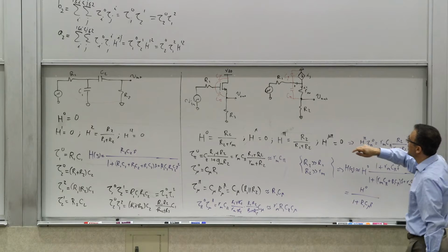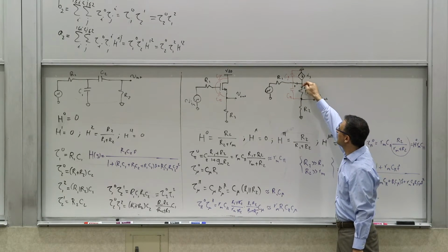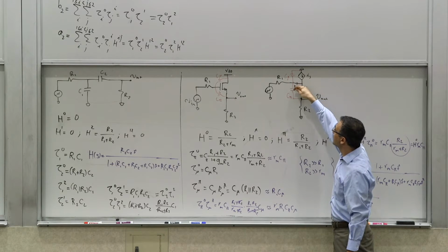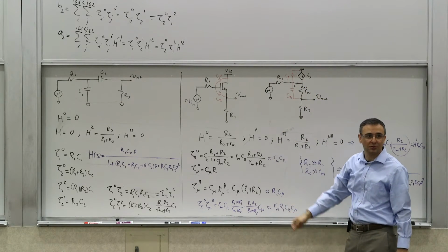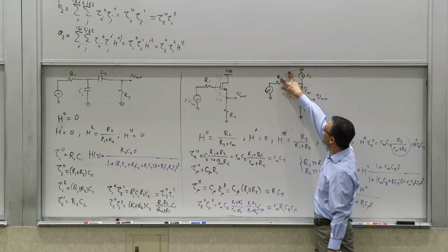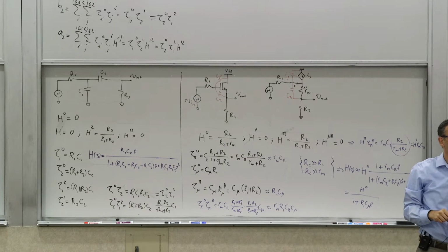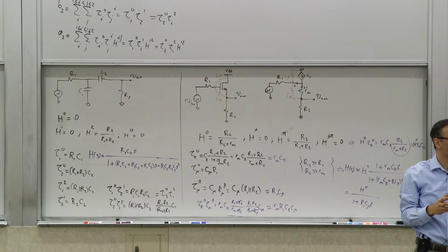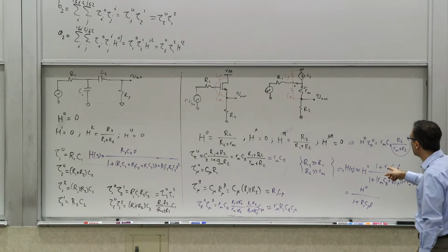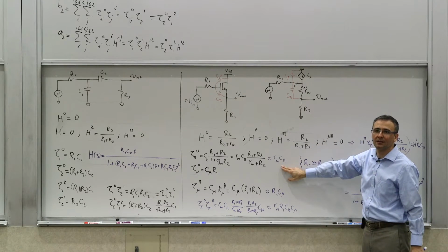And you're dominated because as this starts getting worse through the capacitor, as your frequency goes up, more of the signal goes through the capacitor than goes through the resistor. So it is really the time constant associated with these two, the R1 C mu, that usually can dominate the response of this thing. Because that pole and zero are high frequency, and they're close to each other, and they're around the cutoff frequency.